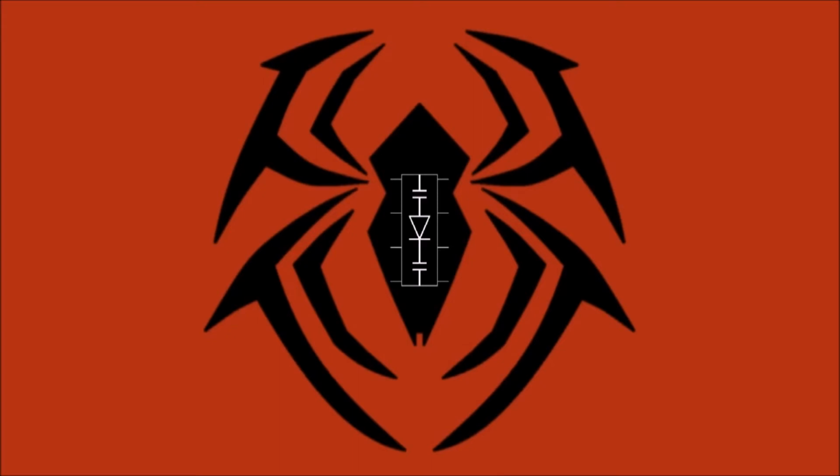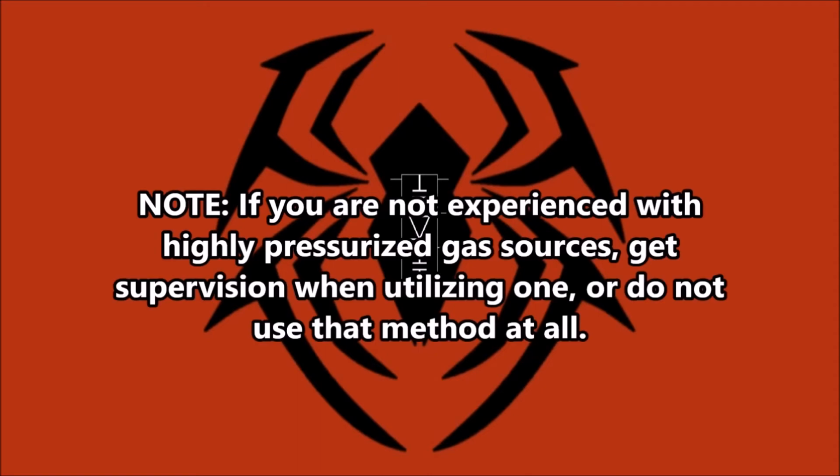In general, about 115 psi should do, and depending on the size of the pressure vessel you're using and what other materials will be interacting with the pressurized formula, you could really go anywhere from 90 to 130 psi. However, going above, I'd say about 150 psi may be pushing it, especially considering the weakness of common materials I've seen pressure vessels made of. However, this is once again going to be up to your own testing and the material that your pressure vessel is made of.